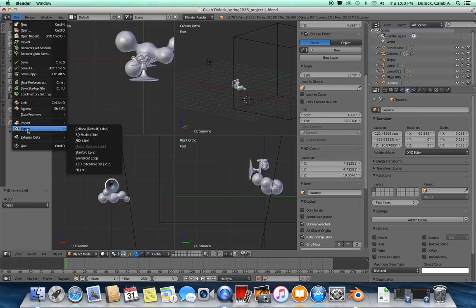We're going to go all the way down to Export, and we're going to use the option called Collada DAE. There are other options here listed for exporting. Wavefront OBJ and STL are formats common to 3D printing. Just as a side note, in case you ever decide you want to try out 3D printing with a model, you can use those. There are other settings, of course, that have to be adjusted for making a 3D model print ready that your model may not have yet. So those are things that you may want to review or look into in the module. I do have a section on 3D printing that you're welcome to look at, but it's not related to work that's required for this project.